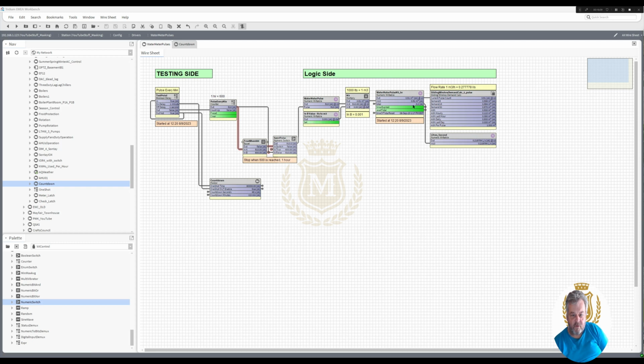I reckon we're going to be using the 1 hour timer that's built into the logic with the numeric totalizer. I reckon that's what we are going to be using to give us our value, because I really want that to be 0.27778 or thereabouts, and it's already 0.22, so I reckon that is going to work. And I believe that this is going to be a load of rubbish for the sliding window demand calculator. But we'll see at the end of the time. Put you on pause again.